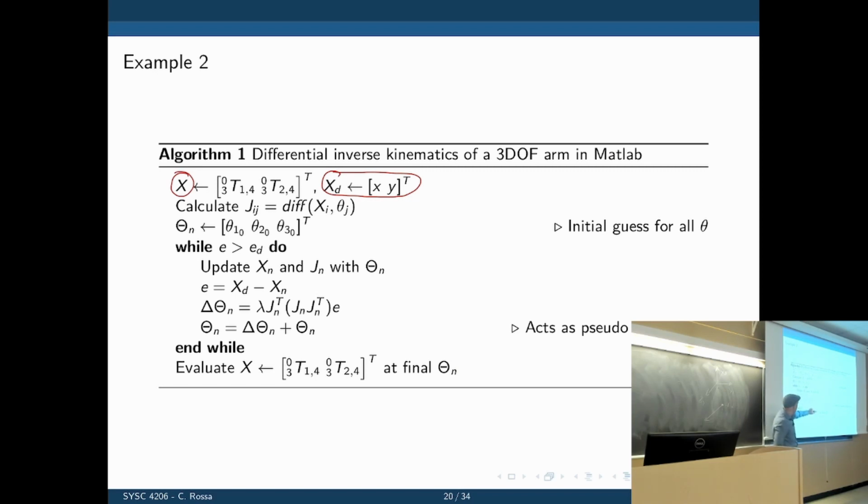How do we go from speed to position? Well, we can simply integrate it. This will act as a pseudo-integrator. I'm simply adding up the speed in every iteration. It's a bit more than that, right? I have to calculate the area in the rectangle, divided by the time. But here, time, or the x-axis, doesn't really mean anything. It could be fixed because we are controlling the step length. So it's enough to simply add the value.